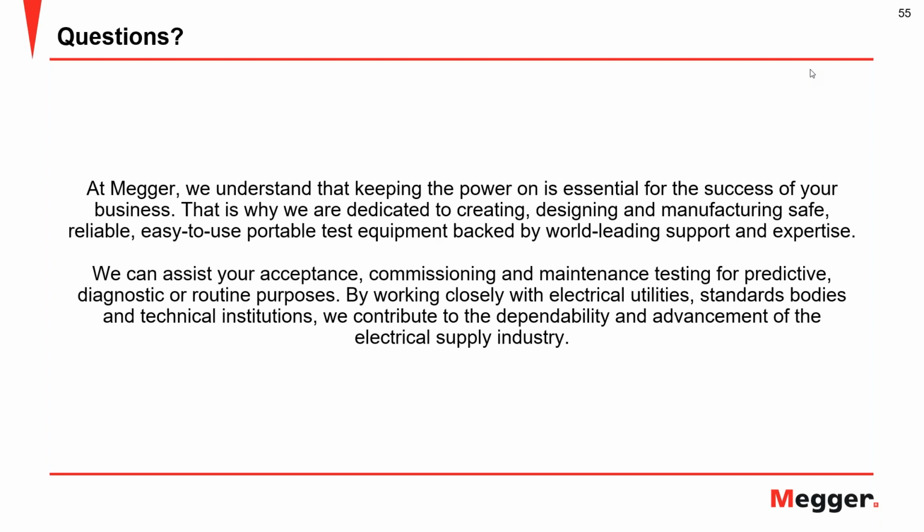All right, thanks, Michael, and good question. There are several different variables to the length at which you can test. There are some limitations on shorter lengths where you may be able to determine if you have partial discharge activity, but may have difficulty localizing it, and that may be more on the 20-meter side. Certainly, I don't see any issues with a 100-meter long cable.